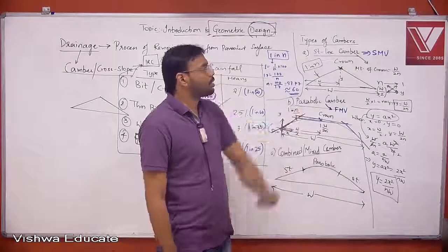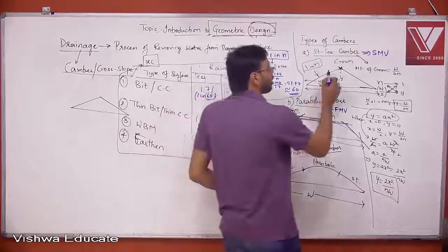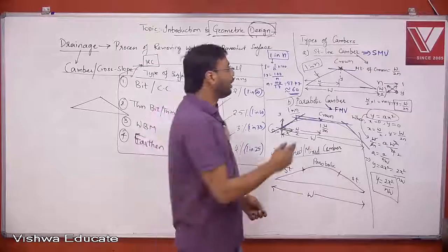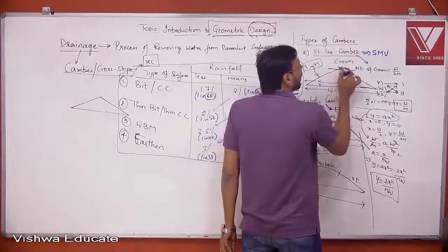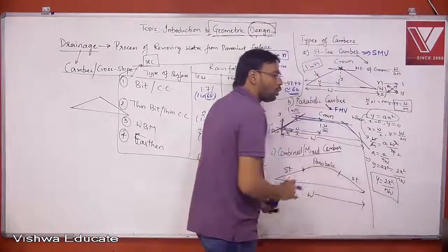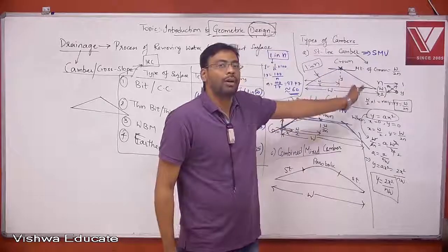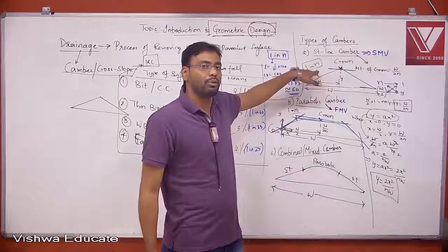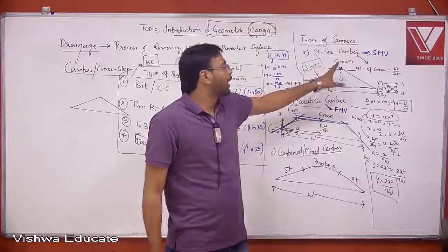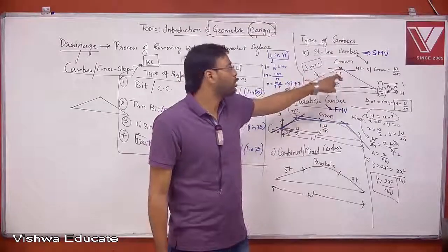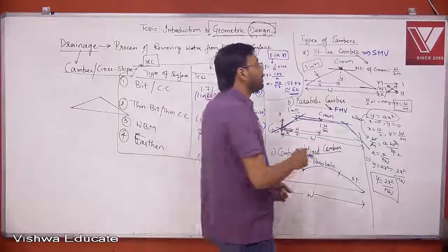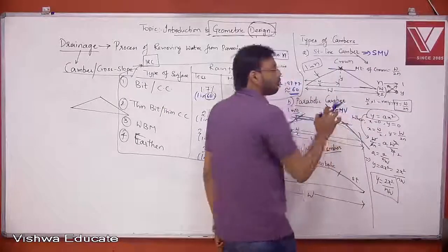Now if you see this straight line camber, this is the center part of the road, and if I want to overtake a slow moving vehicle, I travel this way, then I get down in this direction, overtake the vehicle, and again come back here. So you are getting down from the crown and again climbing the crown here. There is a change of crown movement here, so there will be a small jerk feeling because of this unevenness if you want to overtake in this fashion. So obviously this is suitable for slow moving vehicles, and that is suitable for fast moving vehicles.